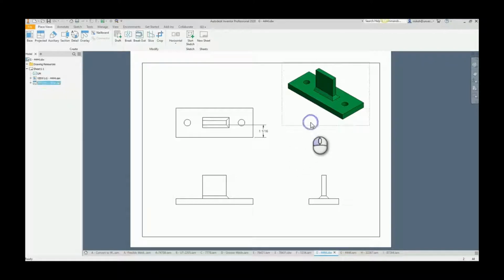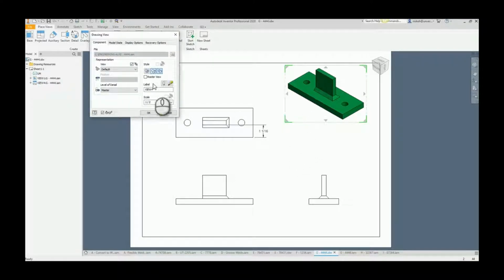So the first thing we typically do, most of our weld symbols are in the ISO view, or we make multiple ISO views to get the point across, because it's easier to see where the welds really belong in an ISO view as opposed to an ortho view. So we typically shade it in, and then in the view rep, here we're going to go in and grab welds. And you can see here's where the annotation contrast color scheme really makes it pop in that view.